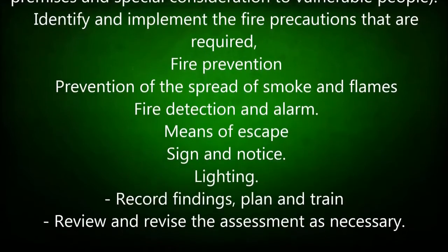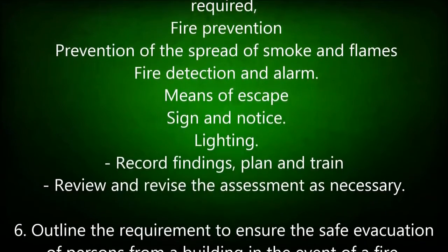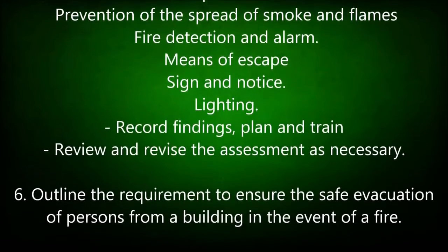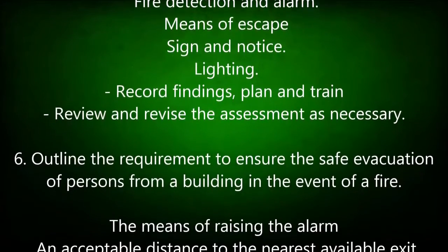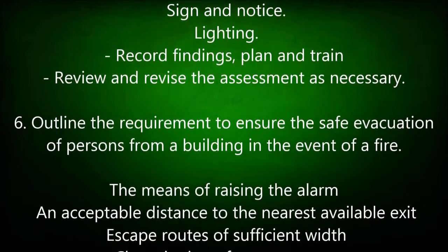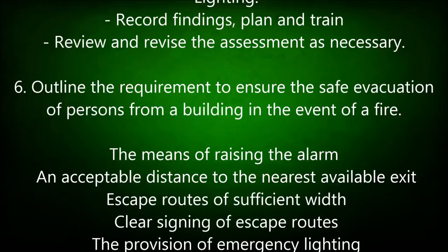6. Outline the requirements to ensure the safe evacuation of persons from a building in the event of a fire. The means of raising the alarm. An acceptable distance to the nearest available exit. Escape routes of sufficient width. Clear signing of escape routes. The provision of emergency lighting.